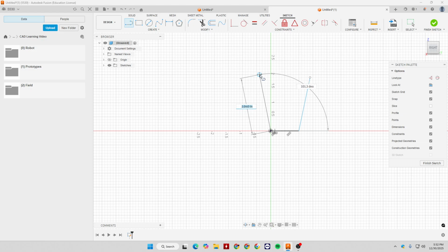So say this is the outer part of something, and we'll have the inner part. When these two shapes are all the way nested, these lines are super close together, and if they're actually touching, you'll have a lot of friction. But with the draft angle, if you take the inner object and release it, you create more and more distance between these side walls, and it becomes easy to release.